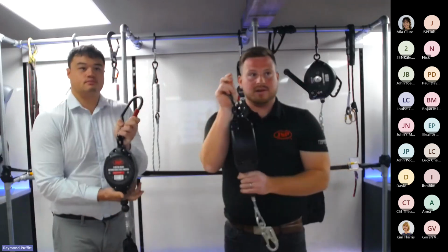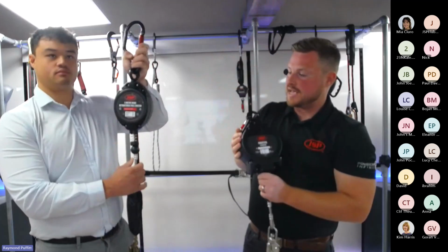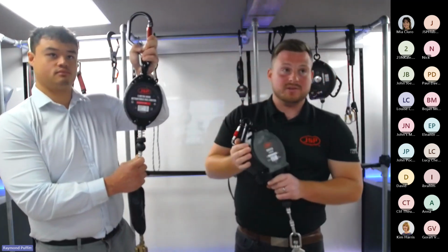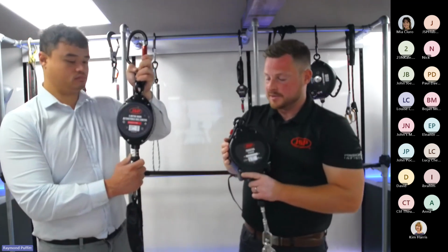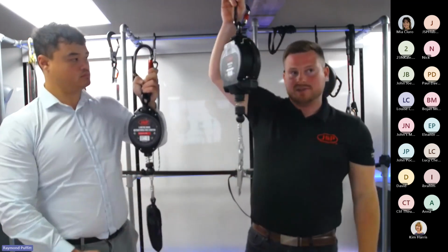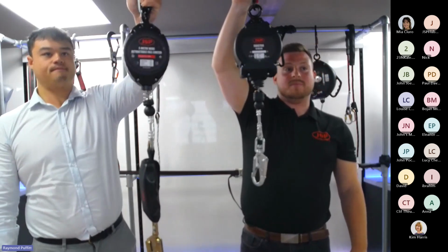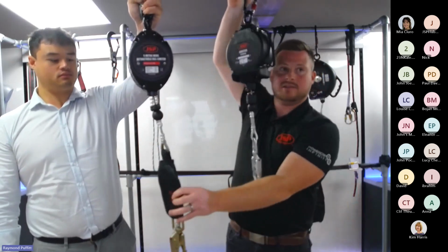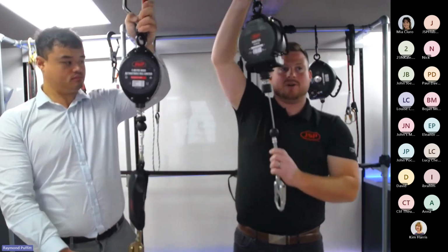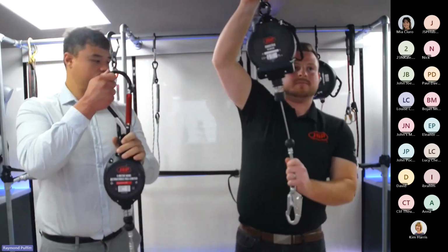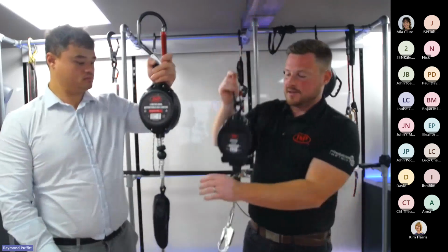So what we have here is I've got just a 10-meter standard block, and Harry has a 5-meter, which has been used, tested for horizontal and sharp edge use. Straight away, if you just hold that up, Harry. Big difference on the two products. The sharp edge lanyard obviously has the shock absorbing pack there. Okay, standard block doesn't, so it works like a seatbelt, locks off, absolutely fine, user keeps moving.